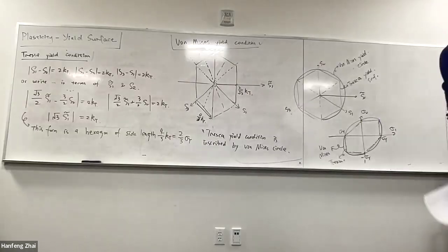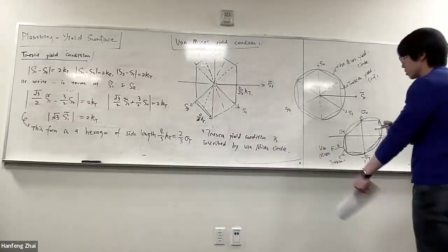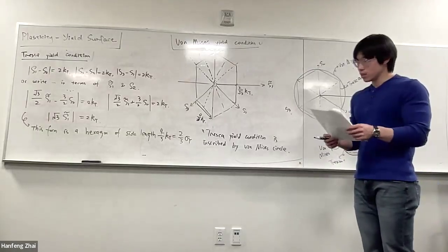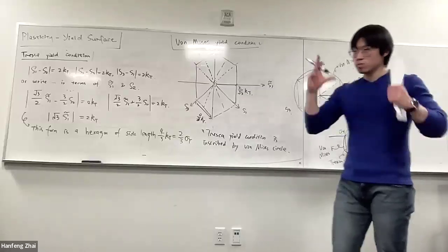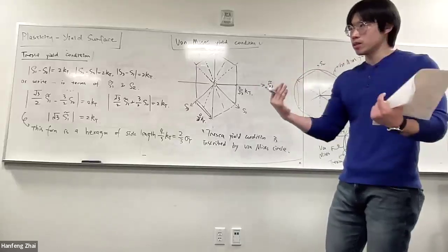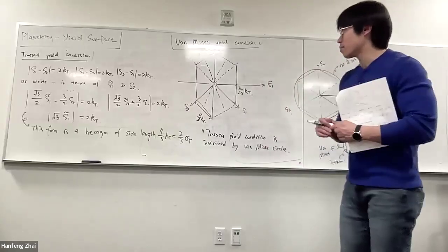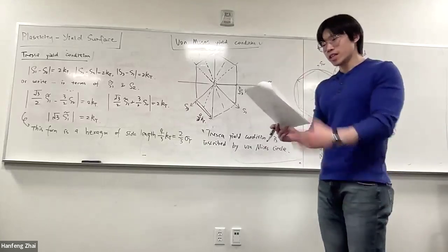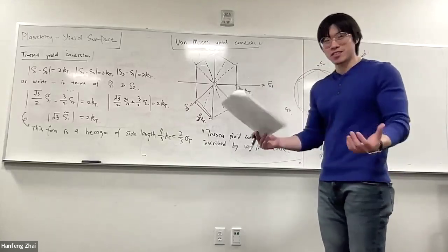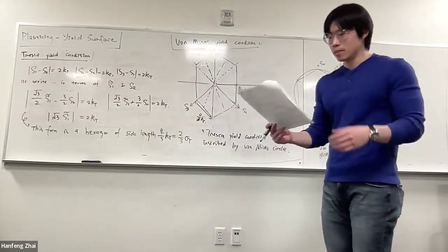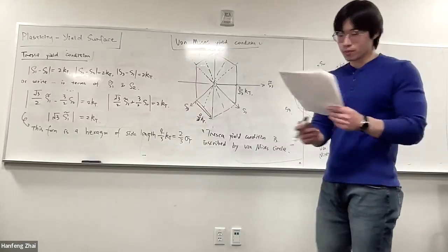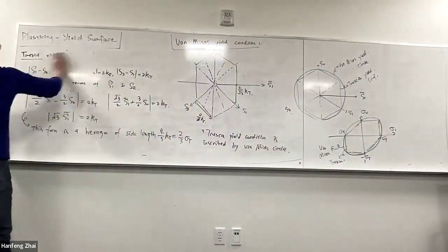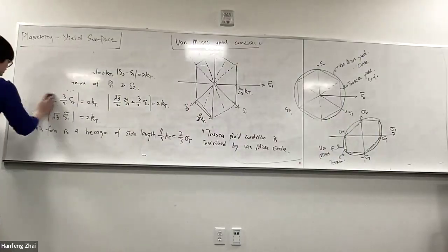Okay, so we have geometrically explained both the von Mises and Tresca yield surface, and shown you what it looks like intuitively, either in 3D or on the projected pi plane. And now we're going to go a little bit deeper, where we actually enter the research part of plasticity, which is a very popular hot topic in solid mechanics, which is the flow rule. And I'm gonna wipe all the equations I have for Mises and Tresca.